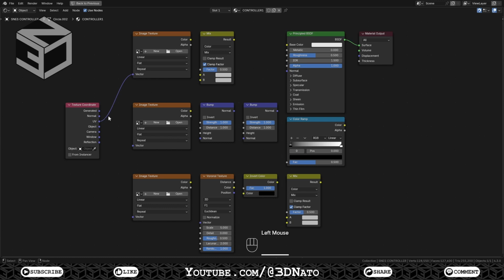Connect the texture coordinate UV to all image texture vector, so they can use the unwrap we did last video. Connect the texture coordinate object to the Voronoi texture vector, so it uses an object as a source for coordinate. Set Voronoi mode to Smooth F1 and the scale to 10,000. This will create a very simple procedural plastic texture for the controller.